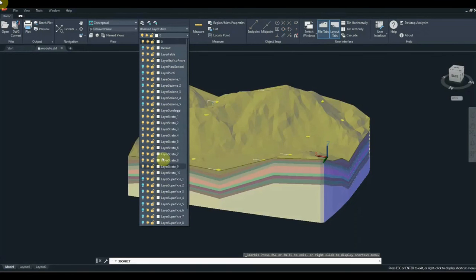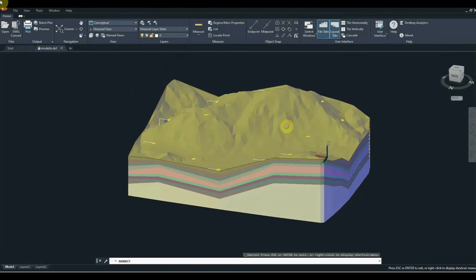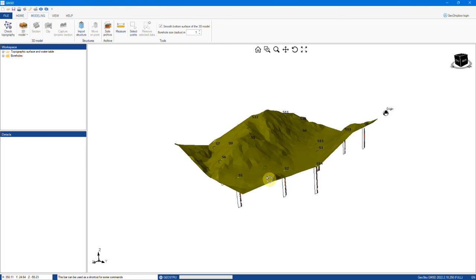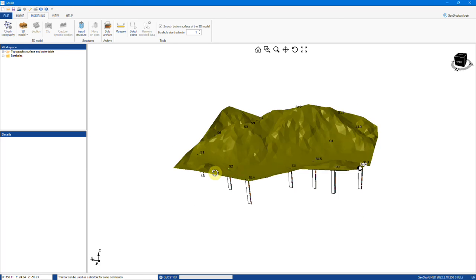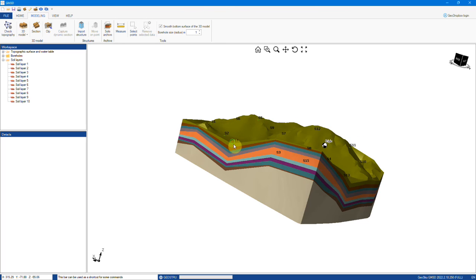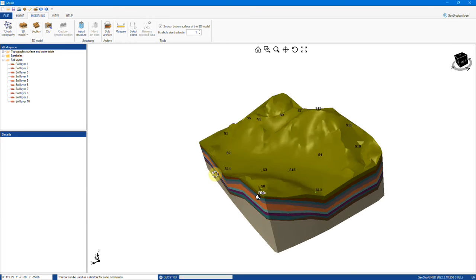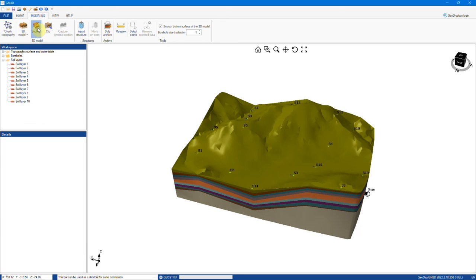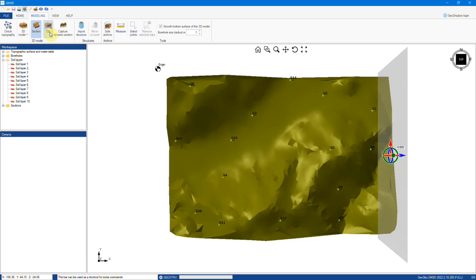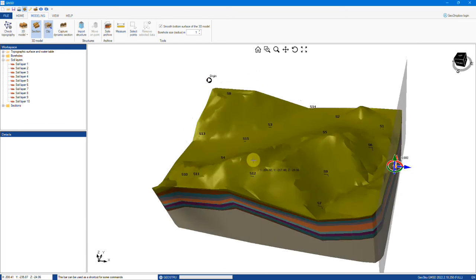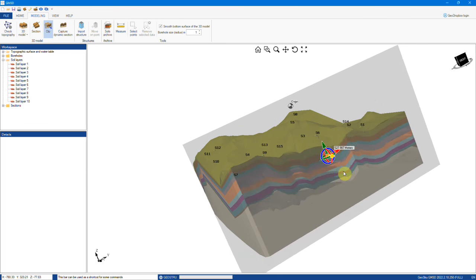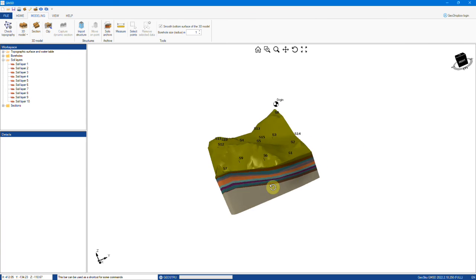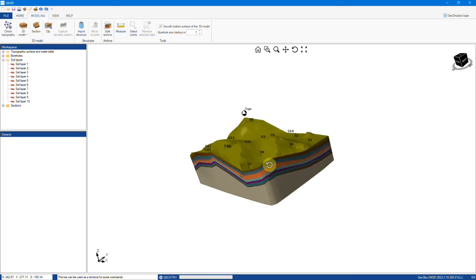In this video, we have seen what the general characteristics of GM3D software are, and how to process the topographic surface, then how to get it through GeoStru maps, and how to build it inside GM3D. We have also seen how to build boreholes and how to import them using files in EDP format, which is a well-known GeoStru data interchange format that allows the export and import of data related to static, dynamic, and geophysical tests.